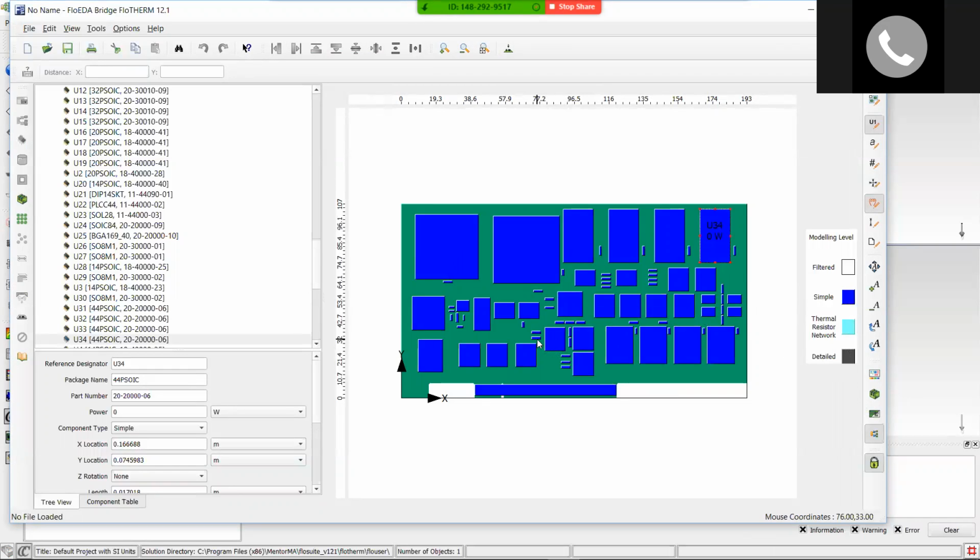The next step you want to do is filter out some components that are not thermally significant. So for example, all these resistors and capacitors, unless they are RF type, they have almost no significance from a heat standpoint. Things like connectors, right? These are passive; they don't generate heat. Okay, they help with relieving heat in some cases, but for signal connectors, those have no contribution whatsoever. So the way to do that will be to do some filtering.